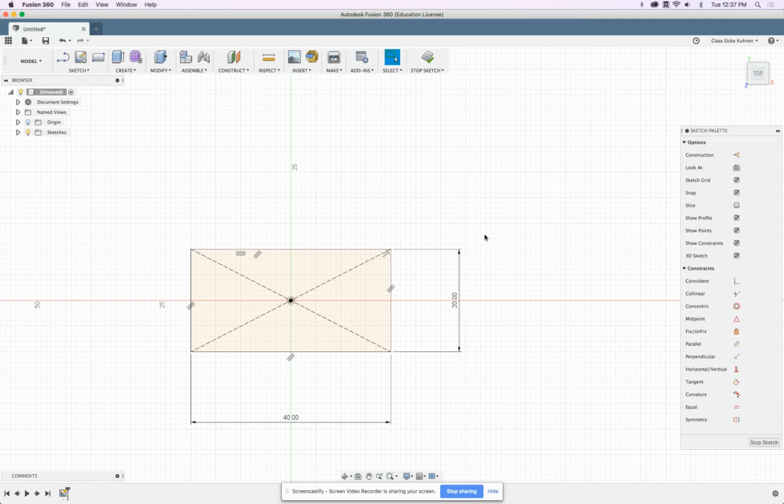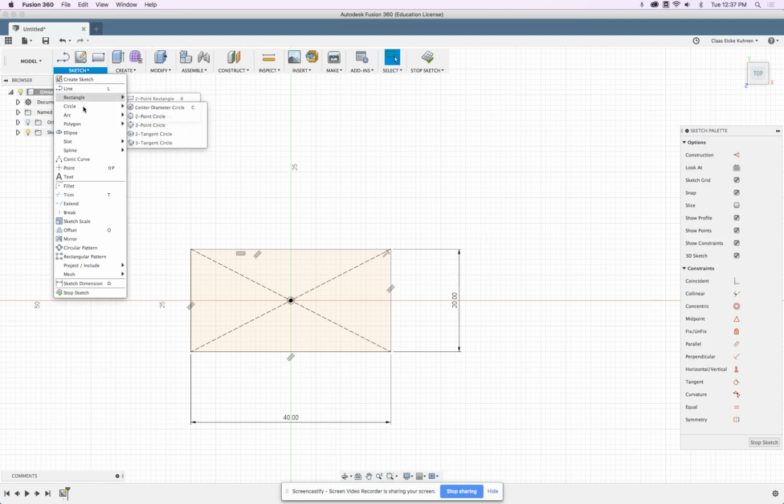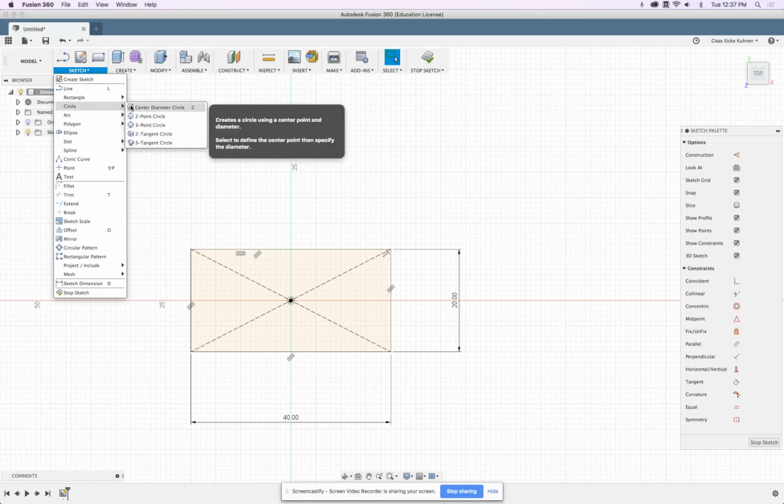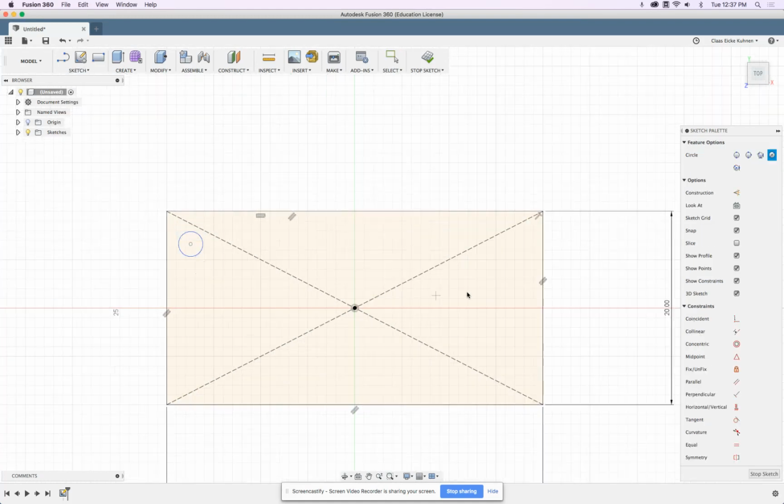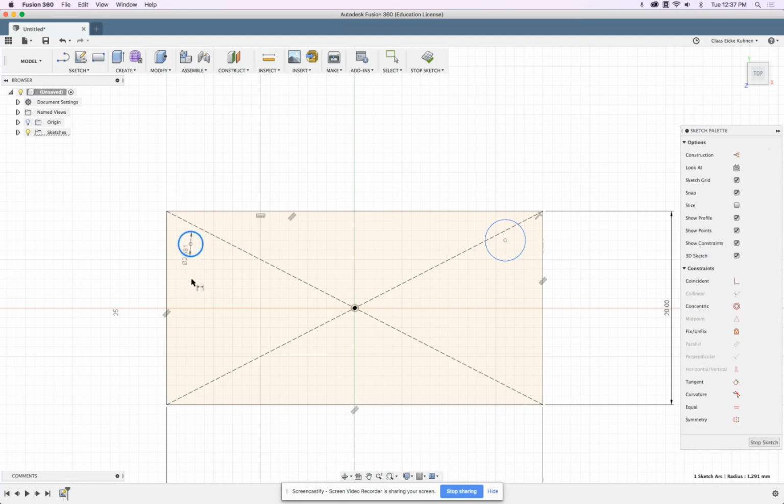That whole object has 2 drill holes. So we will create 2 circles, one here and one there. Each circle we make 4 millimeters diameter. The other circle I don't dimension. I simply say this circle be equal to that circle, and that adjusts already the dimension.